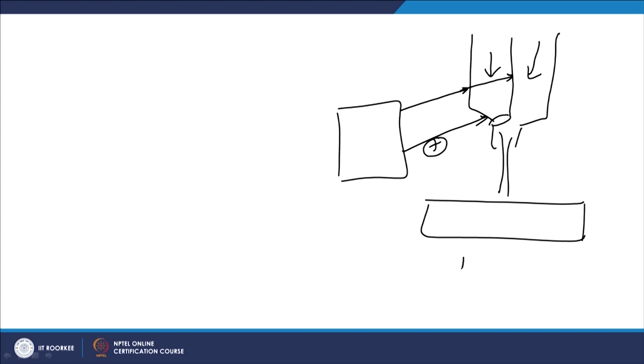This one is called non-transferred plasma. In this case the arc is independent of the workpiece, only the plasma coming out of the nozzle will be impinging with the surface of the substrate.